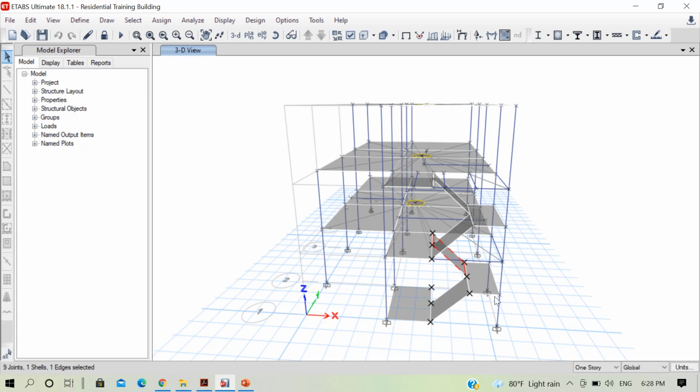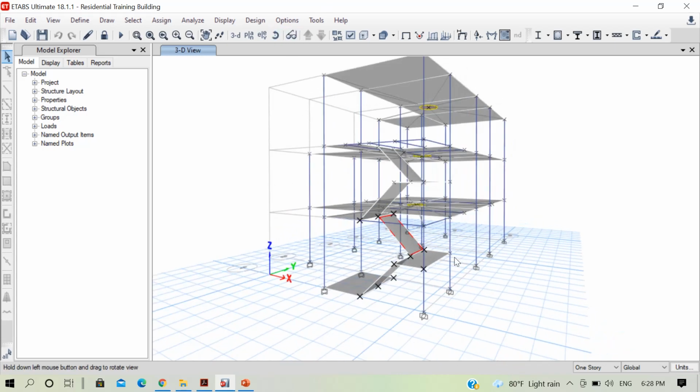We had also modeled hinge joints for these two joints here, where the mid landing slab is connected to the column. This hinge joint is also sort of dividing our columns into two parts, and we were seeing some erratic behavior of the columns. So I also selected these joints and made them free, which means we did not provide any restraint to these joints either.